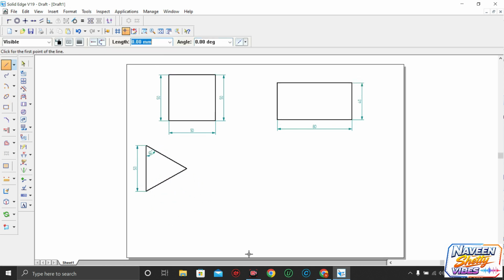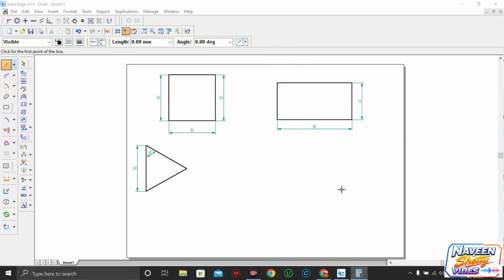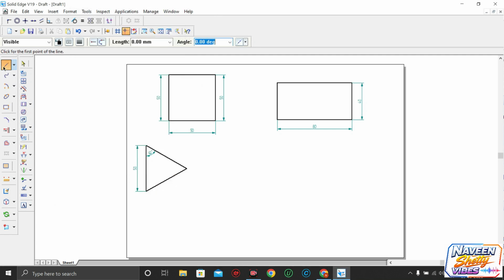And next, if you have to draw a pentagon in a simple way, what you can do is this. As usual, if you have to draw a 50 pentagon, which has 5 sides, 360 divided by 5 means 72 degrees. So now just click on the line, which is 50. Okay, this is 50, and now the length once again 50.